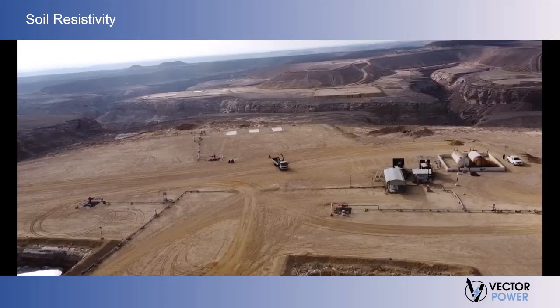Finally, salt content factors in the results in a very big way. Changing the composition by 1% can reduce soil resistivity by as much as a factor of 20. Therefore, a quick visual analysis of the job site can give you a good idea as to whether you can expect low resistance from the installed grounding electrodes made up of a single ground rod, or if you will need to install several rods to achieve the required results.